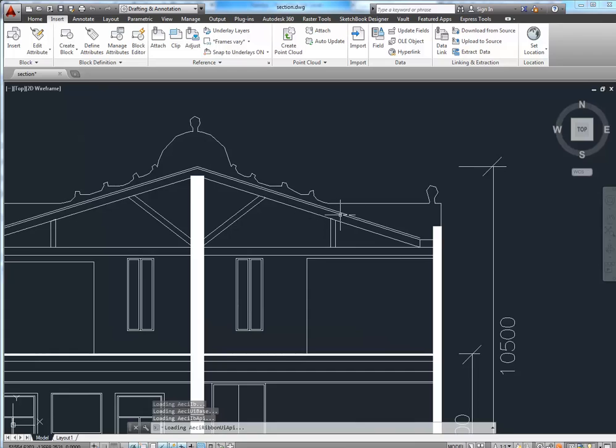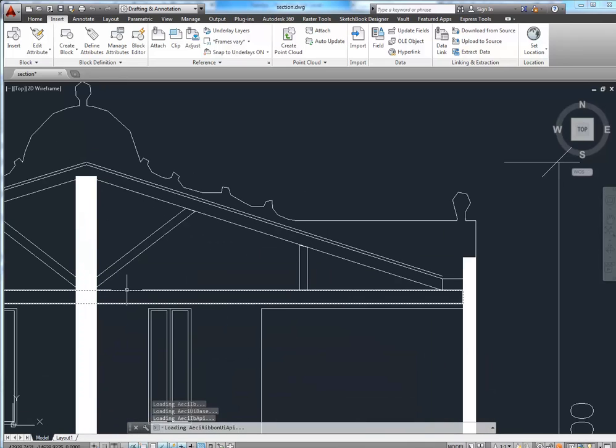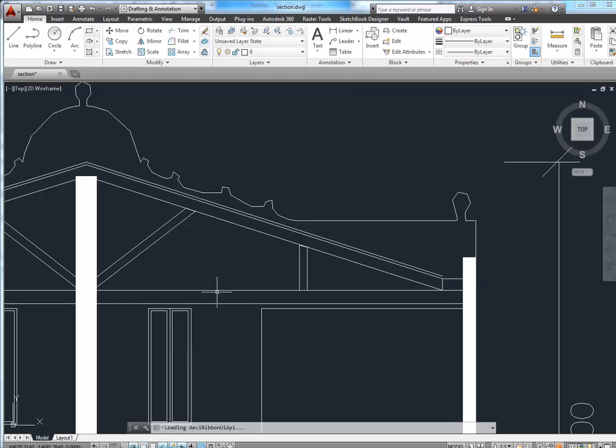Okay, so I'm going to get the AutoCAD drawing. Alright, so you've got the joist, yeah, we'll call it a joist. Essentially it's the bottom of the truss, which is going to function really as a ceiling joist in this case, or a beam, I suppose, you could call it. And then you also have the rafter above that, which is the other main element, which gives the depth of the truss. And then the top of the rafter essentially is your ridge. So that top point there on your ridge is the top of the truss.